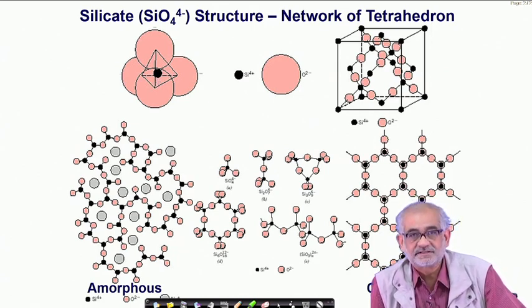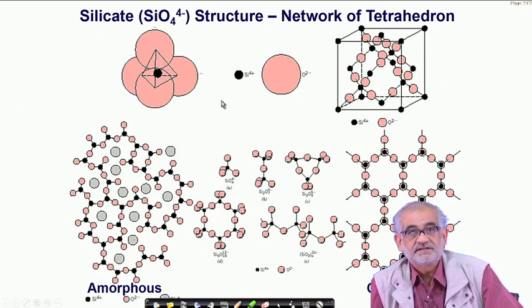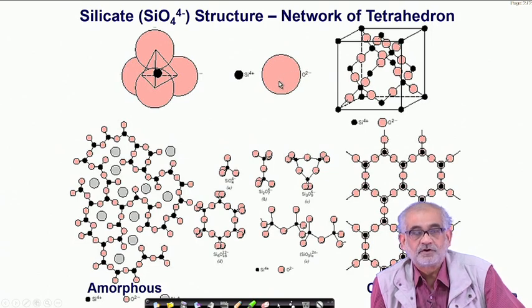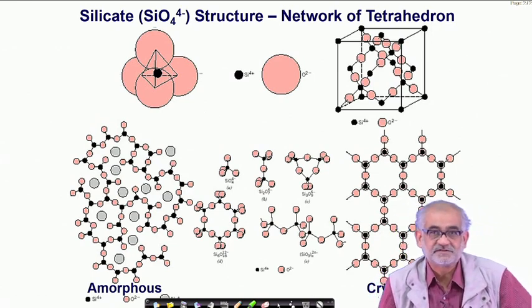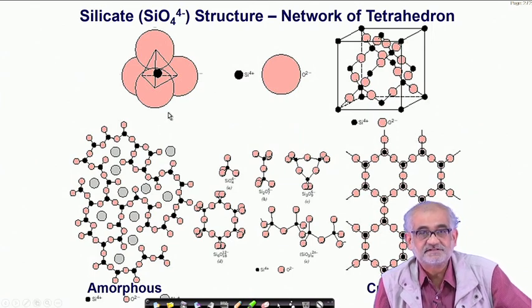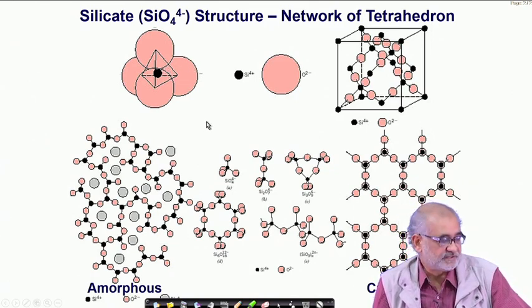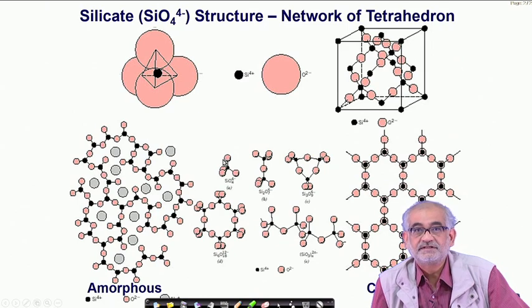And this is dictated by the thermodynamic terms. To be more precise, something called the Gibbs energy, which essentially is derived from the intrinsic property of specific heat, showing up in the form of enthalpy and entropy, and relative contributions of enthalpy and entropy actually decides what is the relative Gibbs energy of a particular phase in a given system. And depending on the Gibbs energy, relative Gibbs energy, and to be more precise, the chemical potential, one actually decides whether a particular phase is going to be stable or not. And structure does play a role in determining such stability.